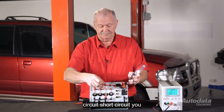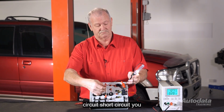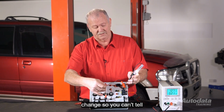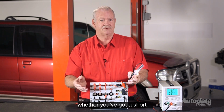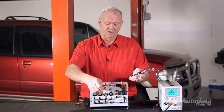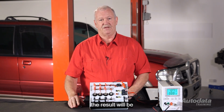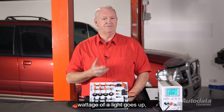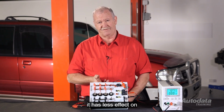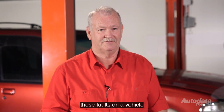No short circuit. Short circuit. You can see there's virtually no change. So you can't tell whether you've got a short circuit or not with a low wattage test light. The higher the wattage of the test light, the better the result will be. This is because as the wattage of a light goes up, its resistance goes down, so it has less effect on the circuit. Let's have a look at a couple of these faults on a vehicle.